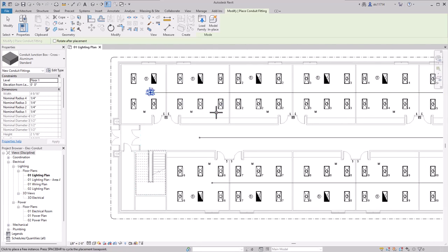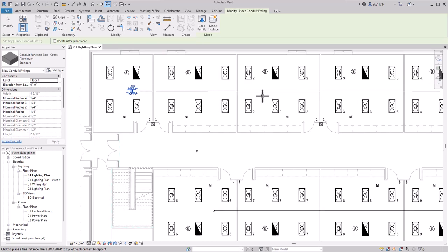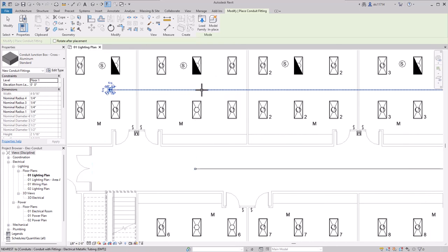And the textbook will tell you to add additional ones in classrooms as needed. Technically, we should probably have a junction box in each room because we've got the power running through these conduits, and then when they get into the rooms, the wiring needs to go to the actual lights. So there needs to be a way to come out of there.